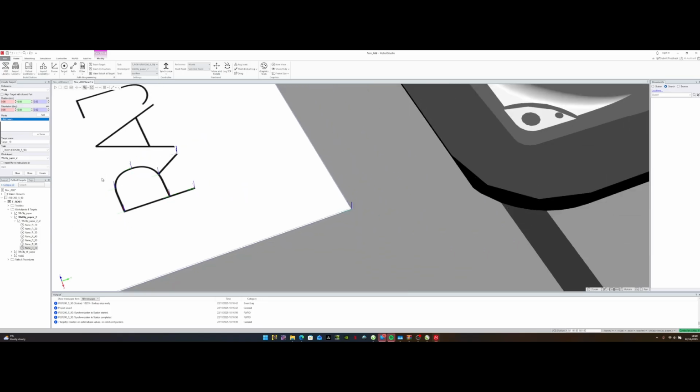So let's go on and create all the other robot targets. So I'm going to go back, world reference, work objects. Okay, click on add new, and then I'm going to create my letter A. Letter A is the simplest letter because they're all move linears. So I can make it that the robot goes 1, 2, and then I want to come back here and draw the cross across it.